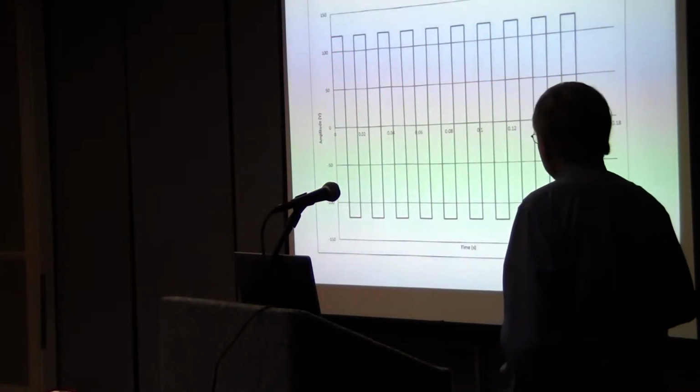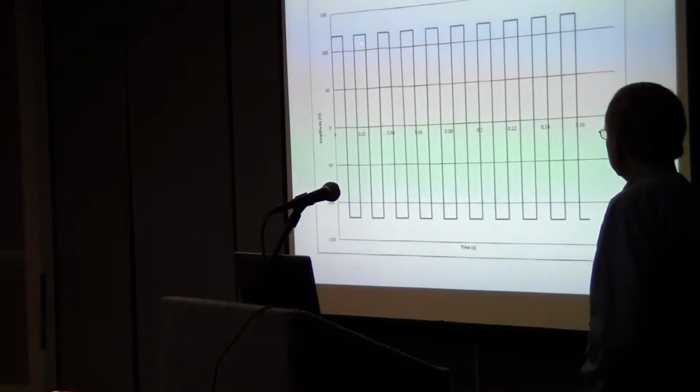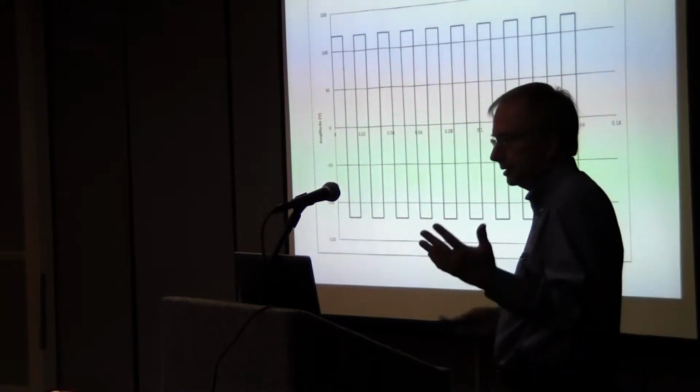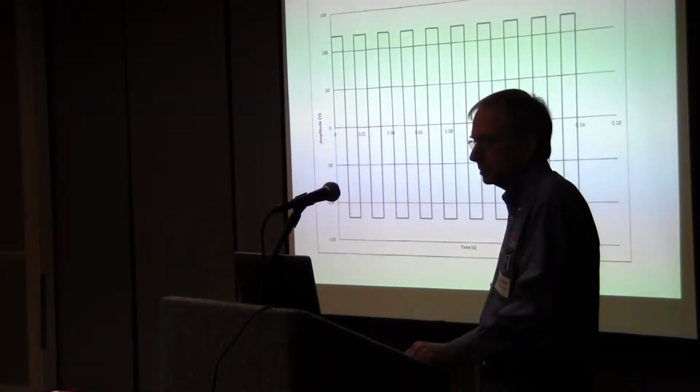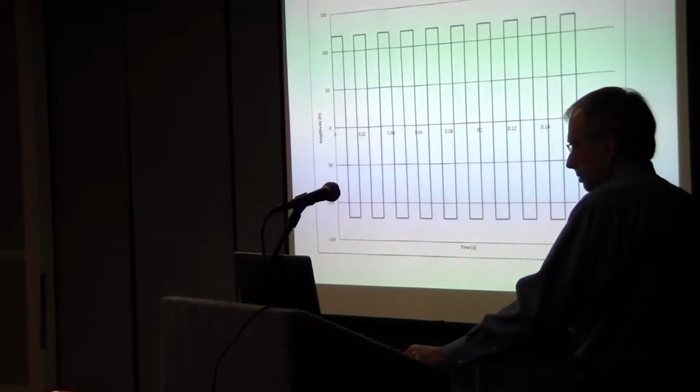And if you think about it, it's 120 volts RMS, because if you rectify this thing and take a minus 120 and put it up here like you would in a rectifier, then it becomes 120 volts DC. And so it's pretty easy for a square wave, like I've drawn here, to know what the RMS value